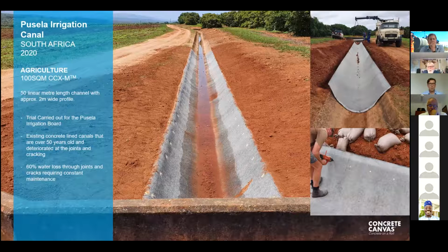The overlaps were thermally bonded and penetrations were sealed with epoxy to create a highly impermeable liner. The remediation of this canal was completed in the space of only 2 hours by a team of 4 installers.